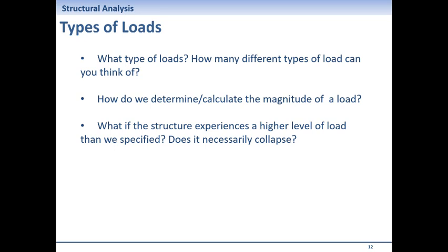In fact, if you were doing engineering probably 70, 80 years ago, even more recent, 50 years ago probably, definitely before I did engineering, but I don't know when exactly, everything else was categorized as live load. So we had only two main categories, dead load and live load. And everything else would be a subcategory to live load. So wind, earthquake, hydrostatic, everything else would be part of the live.